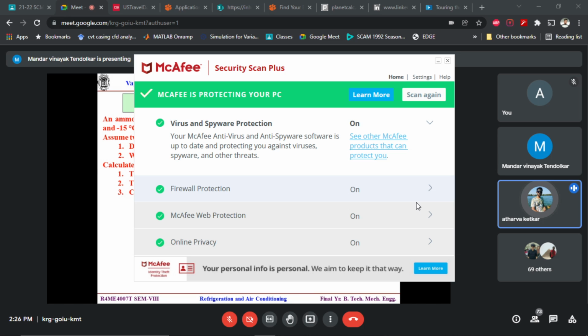So how do we interpolate between the temperature lines? Vertical lines, horizontal interception, linear interpolation. 35 means between 20 and 40. 20 degrees temperature vertical line, 40 degrees temperature vertical line. Linear distance, horizontal distance. You want 35. 5 out of 20 is 1/4. So 1/4 of the distance away from the 40 degrees Celsius line.